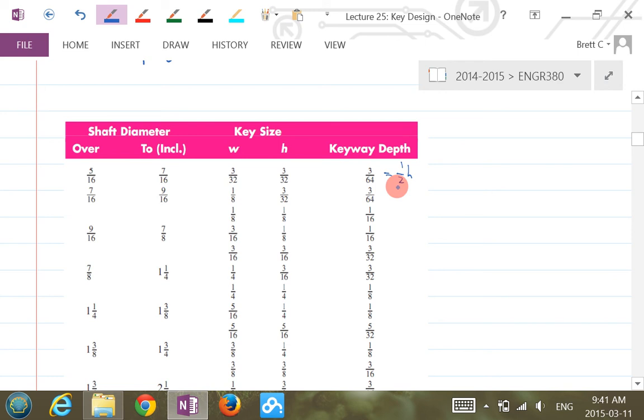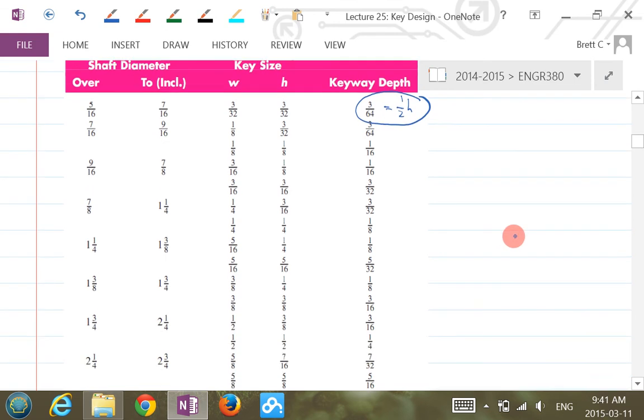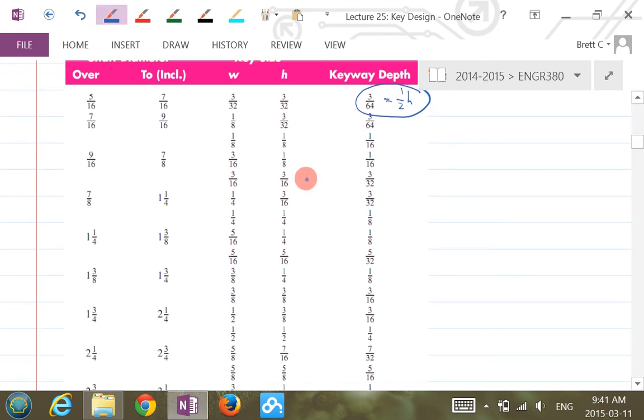Okay, so when you design the dimension for the key seat or the dimension for the hub key way, that's one thing you need to stick to, right? So similarly, you have some other recommendations, but based on this second rule here, you have two recommendations. You can either use this set or this set. So you can either use a parallel key or a square key. That's what table 7-6 is telling you.